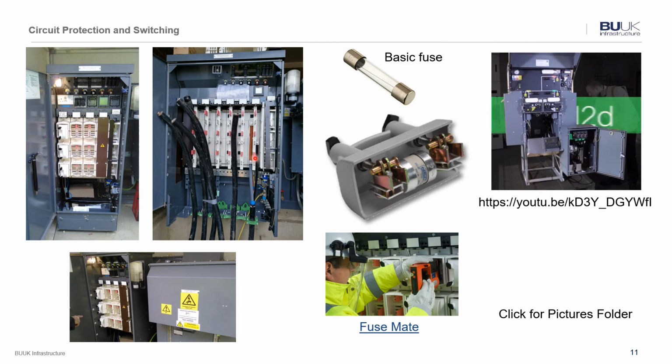Here you've got more. Here is our three-phase conductor, so you've got L1, L2 and L3, and they're each connected with their own fuse. So there's three fuse carriers, one for each of L1, L2 and L3, going out and then coming out at the bottom of the substation and going off to individual customers.